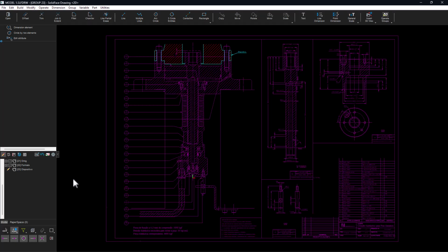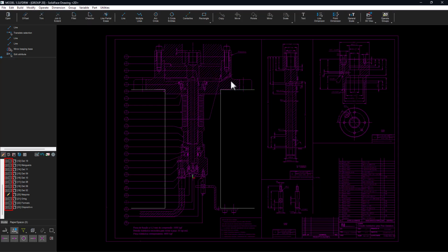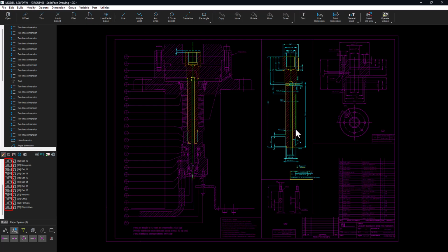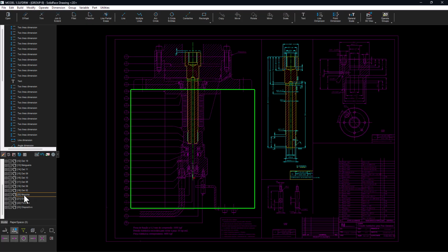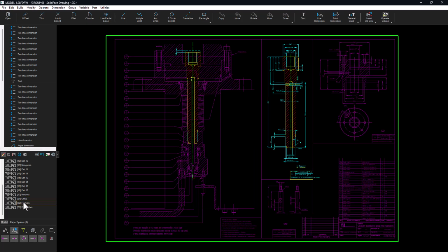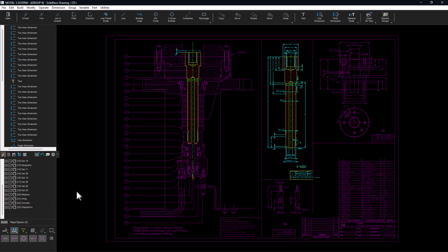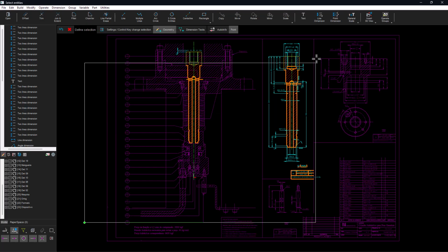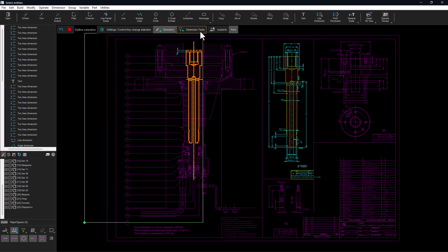To activate a passive group, simply double-click on an entity belonging to that group, double-click on its position in the group list, or on the icon with the symbol. Moving the mouse over the group list, a rectangular area is displayed that contains all the entities of that group. Disable the passive group colors visualization. You can only select entities belonging to the active group. When a rectangular selection area is created, all passive groups will be displayed in passive color, indicating that their entities cannot be selected.